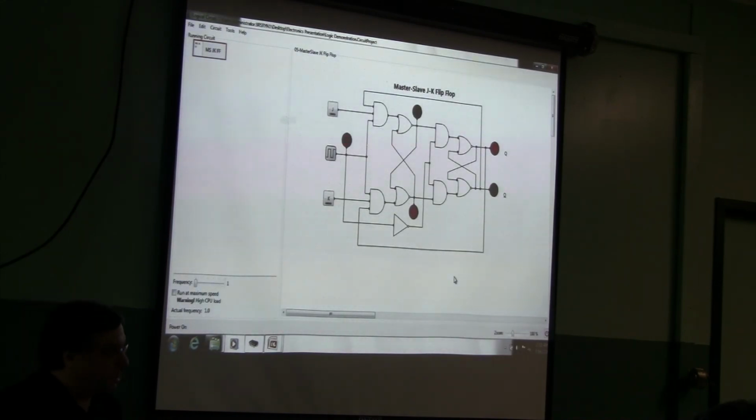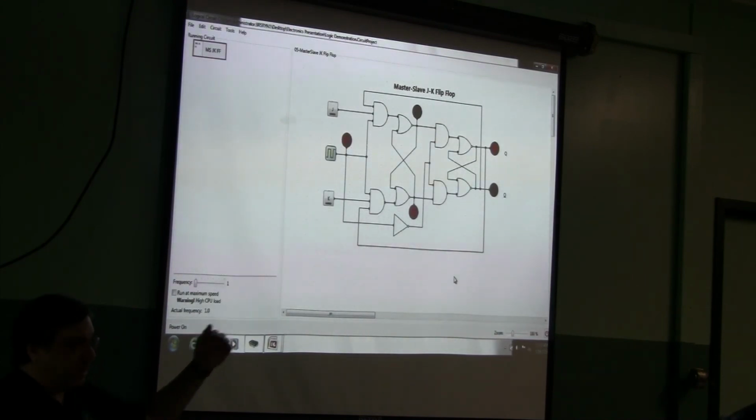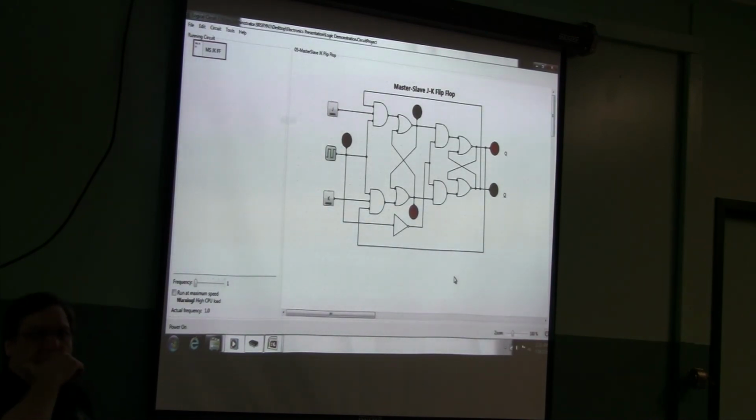Now there are some CMOS chips, 4000 series chips, that have a quite a bit wider range. I don't know the specific limitation, and I don't know if it would go down as low as 3.3, but it'll definitely allow you to go to much higher voltages, I think up to like 17 volts. And there are newer generations of CMOS chips that have adopted the 7400 numbering. So if you get 74LVC series, those are usually 3.3 and below. Okay, so a newer generation that provides the same function but gives you a lower voltage. Right. Look for the letters in the middle.